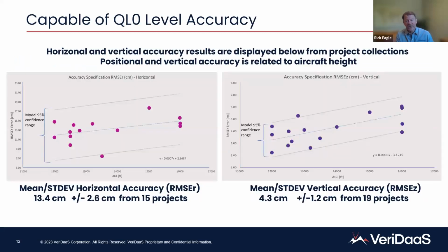In addition to the high definition and the product density, we also end up with that registration process that we talked about earlier, very, very accurate data. So all of this data, no matter whether we're flying at 10,000 feet or up to 16,500 or 18,000 feet, is always going to be QL1 data, always well within a 10 centimeter vertical accuracy and a 30 centimeter horizontal accuracy.